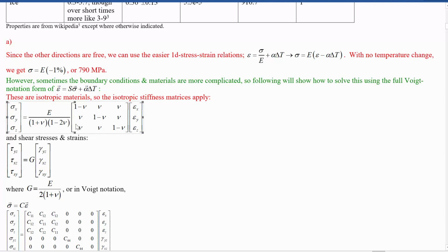So you expect the matrix to have this kind of a form in symmetry. This is the stiffness matrix that we calculated for this type of material after introducing what Poisson's ratio was and how it couples one axis to another one.